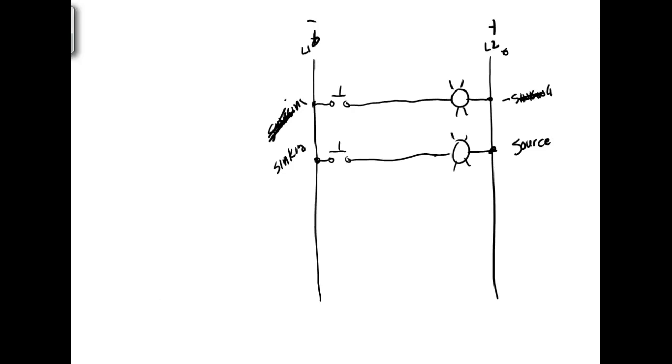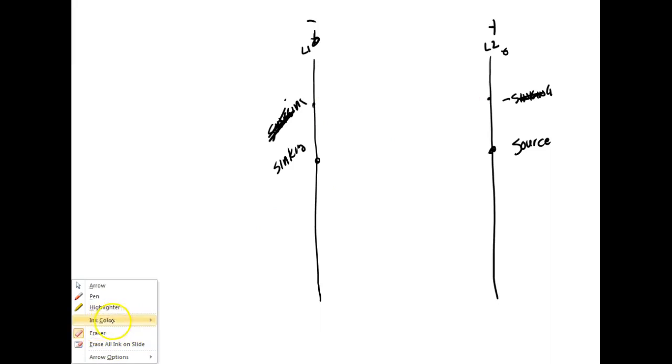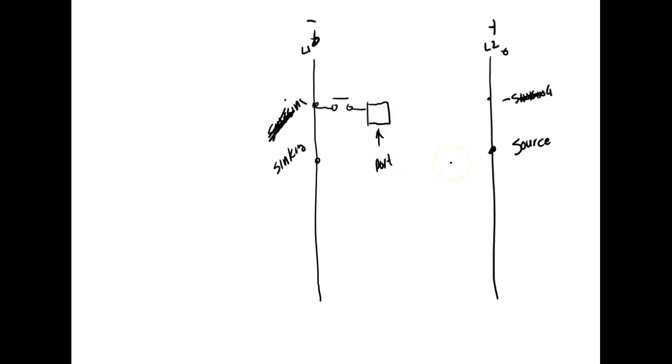Okay. So what that means is if I come over here and do the way we would connect the PLC. What I would do is take my input device, no matter what it is, and we've got all types of input devices, I'm going to put it right there. But now it's going to connect to a port on a PLC. Single bit port. Now, if this right here is positive, I've got to get current flow.